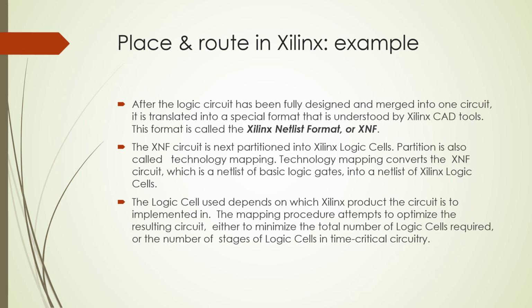In technology mapping, it converts the XNF circuit into a netlist of Xilinx logic cells. The logic cells used depend on which Xilinx product the circuit is implemented in. But the mapping procedure is either to minimize the total number of logic cells required or the number of stages of logic cells in the circuit.